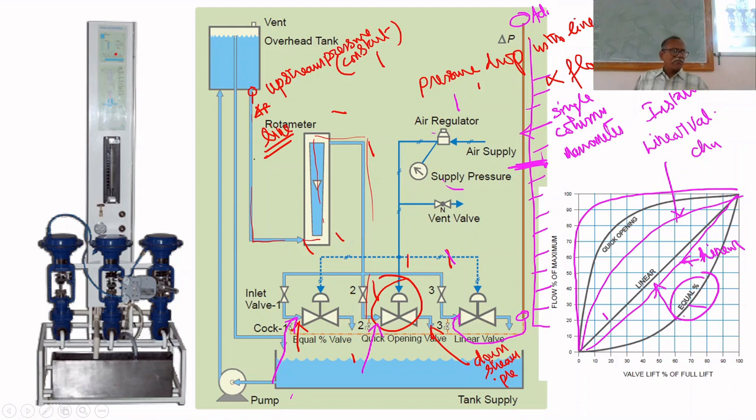Most of the pressure is dropped in the line, so less pressure just before the valve, and the water column will be less in height. For maximum flow rate, the pressure drop in the line will be maximum, and at that time the water column height will be minimum.